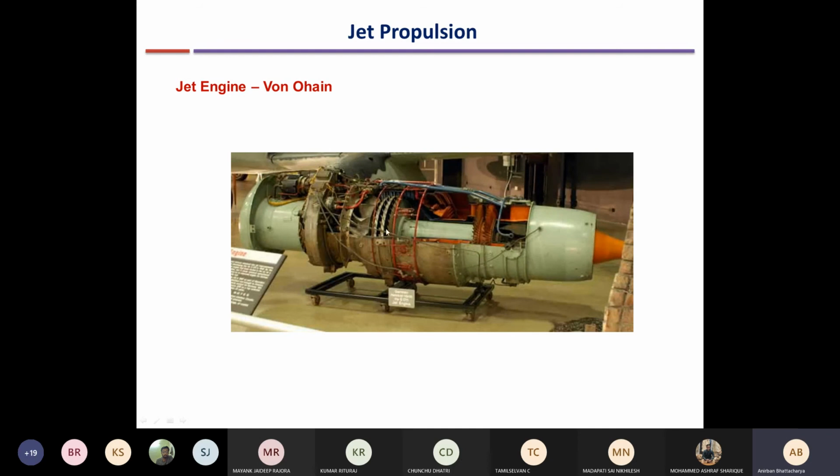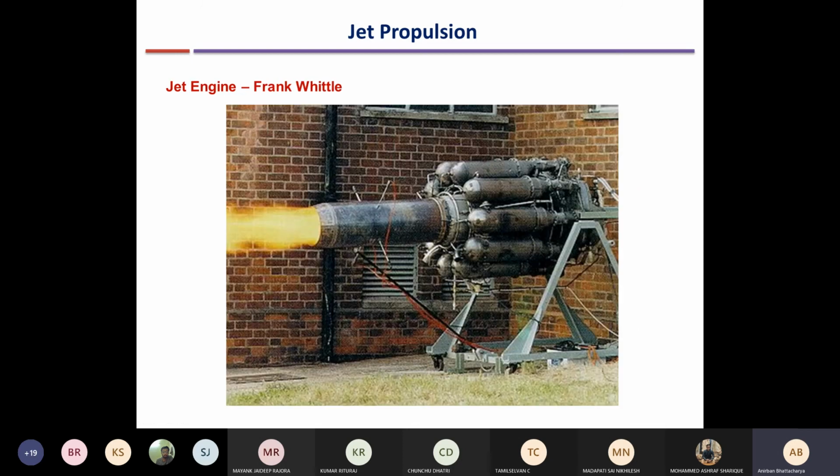There is a series of axial compressor stages. I can see 3 stages here, and then there will be some combustion chambers which are not shown here, and then here you can see a couple of turbine stages. And then there is a nozzle through which the fluid is accelerated. This type of design was generated towards the late 1930s and early 1940s and became quite popular.